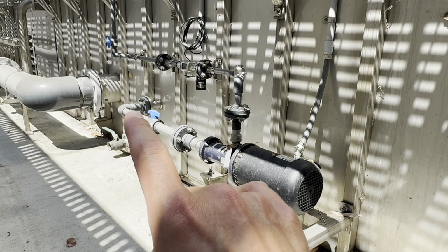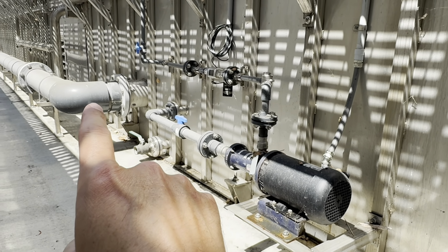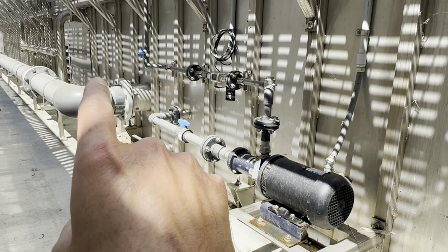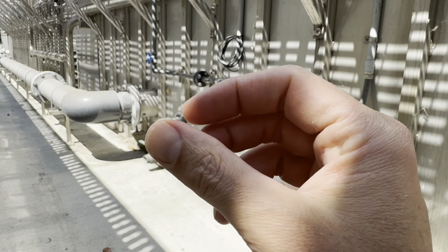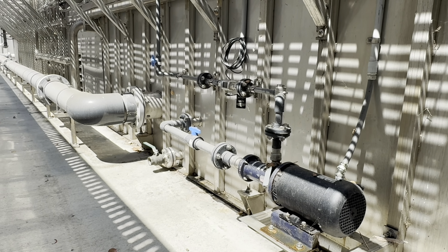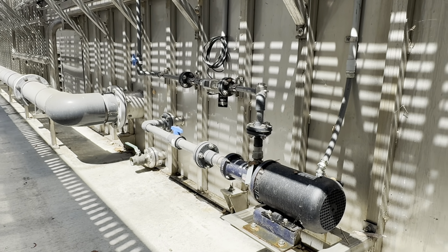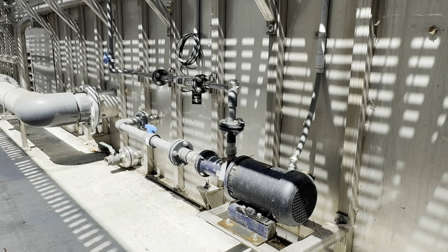And the other thing that's interesting about this is I've got two separate lines. Sometimes you use the same line and there'll be valving. So if the RAS line has a tap on it, you can just valve up the WAS line to take a little bit off the RAS. And so the WAS is how we manage how much biomass we have in the plant.